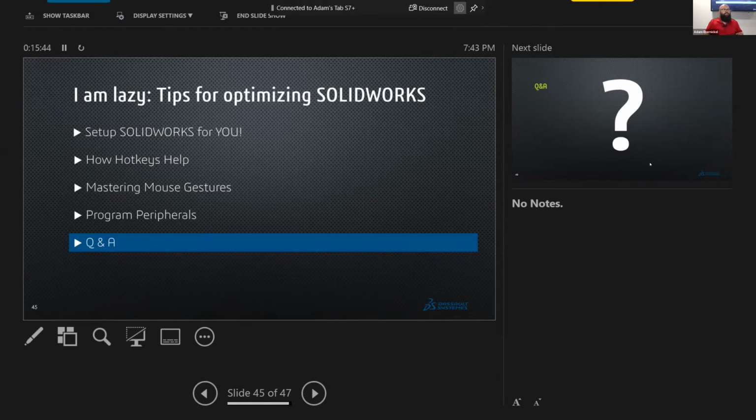We need to match everything to fix all our downloads. Ooh, that'd be hard. Have you heard of 3D Interconnect though? Okay, so 3D Interconnect is a thing inside of SolidWorks. I think it started in 2019, where it will open non-native CAD files. So it'll open an Inventor or a CATIA or a Pro-E or Creo, I guess is what it's called now. And it'll open it in there. So you don't have to get a STEP or an IGES or a Parasolid and have to fix all the mates or fix all the faces.